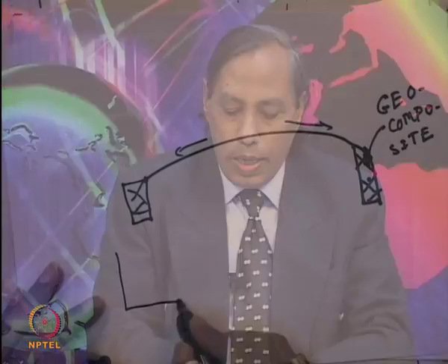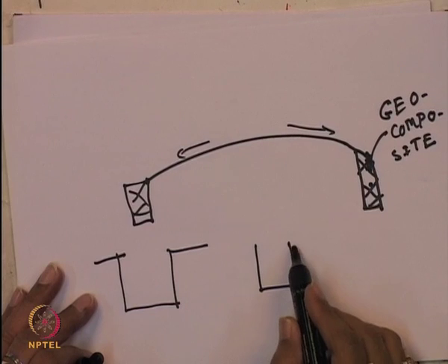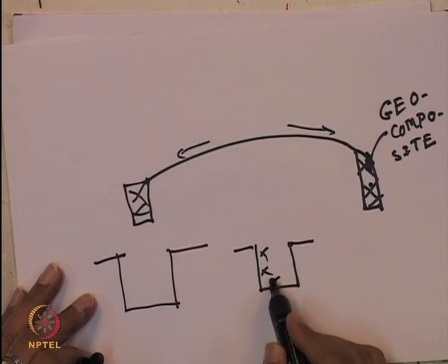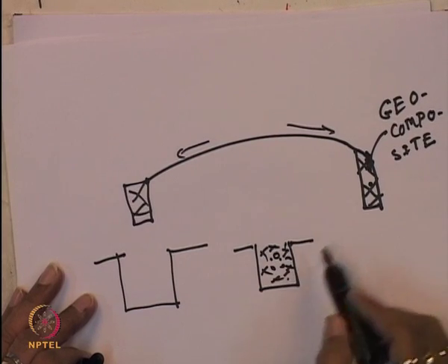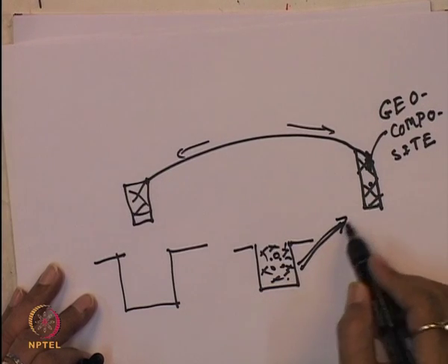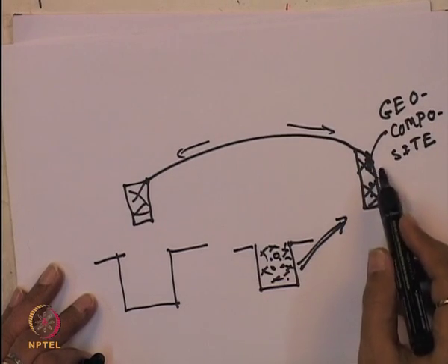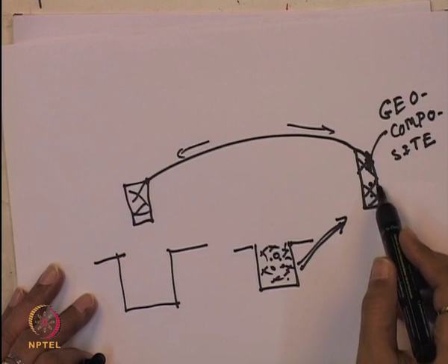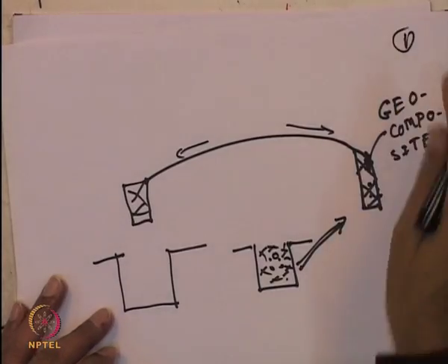As you do with the conventional type, you can reduce the area and the geotextile material and aggregate here, so you don't need it. Instead of this, you can adopt this kind of system with this geocomposite. We can say geocomposite in highway as an edge drain, and this was also reported by Dempsey in 1988.